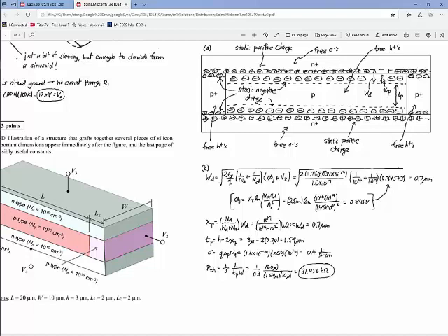Yeah, between P plus and P, I think there is a small depletion region. Well, there's not a depletion region. There's just a small hump in the energy diagram. Right? So you could call it a small hump there, but that small hump is not going to prevent current from flowing. Anytime I have P plus with P, the current will still flow across that.